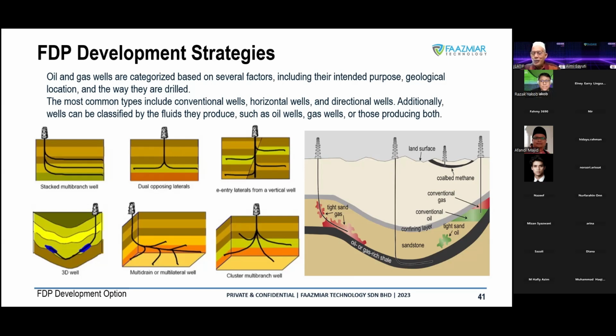With the RSS system, we are able to rotate the string, and rotation of the string means better hole cleaning. So the revolution of technology using RSS helps a lot in drilling to reduce time, avoid drilling problems, and hit the target within a shorter time.